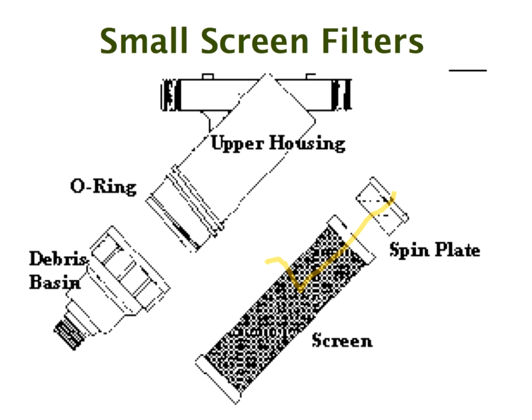And under pressure, the mesh of the screen will expand a little bit. So any bacteria slime that's caught in between the mesh gets trapped when you switch off the flow, and it closes and traps that bacterial material in the screen. So even when you backflush, it's very difficult to get it out.